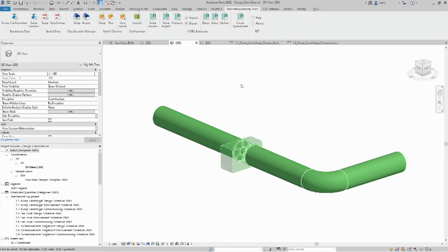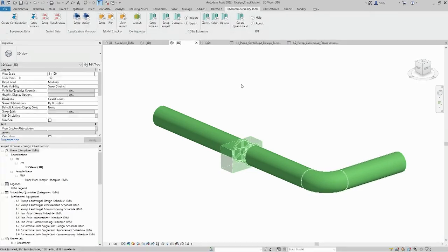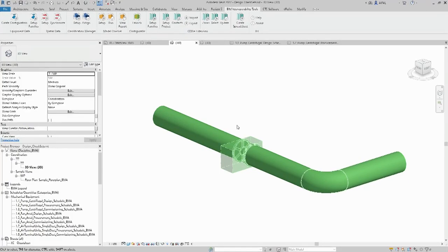Here, a very small system, a little example. I again used one of the BIM-Boss generic families, a fan. And now I want to check how good the quality of that model is. So up here we have the BIM interoperability tools. You can download them when you log into your Autodesk account. On the left side you have product updates, and then under Revit 2023, 2022, you have the BIM interoperability tools plugin that you can download from there. It's completely free.